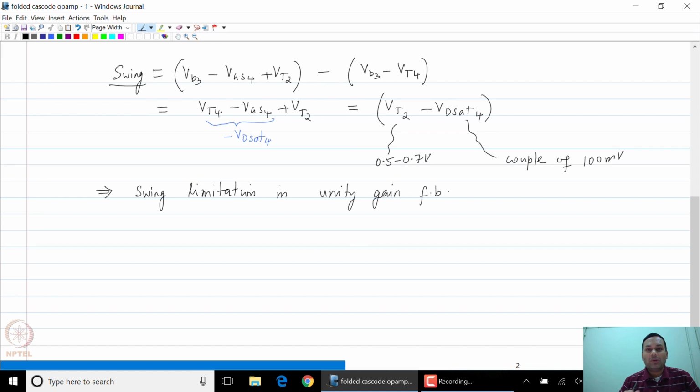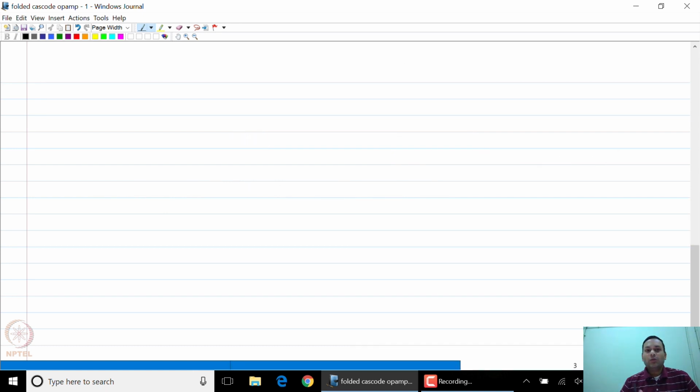So this is a classic problem with telescopic op-amps. Now we want to figure out how to fix this. Hence you need a different type of op-amp. So now we will redirect our attention towards the other kinds of cascode structures we have seen before. So remember, the cascode structure can primarily be broken down into a common source plus a common gate structure. So that is exactly what a cascode structure is.